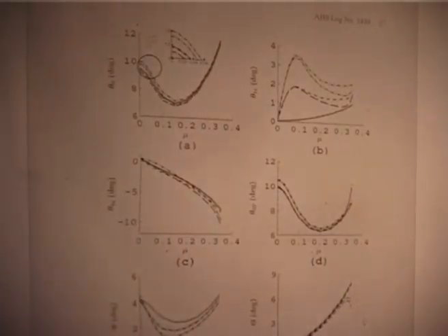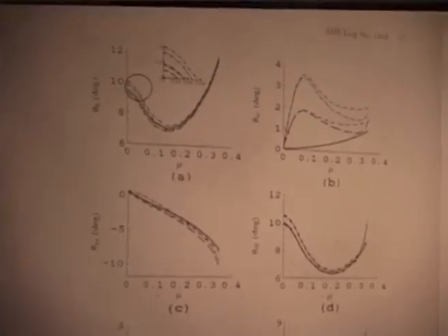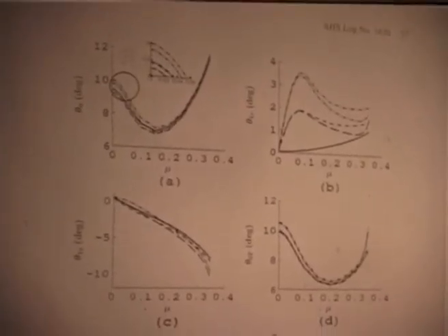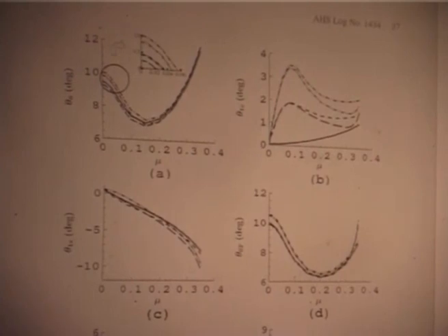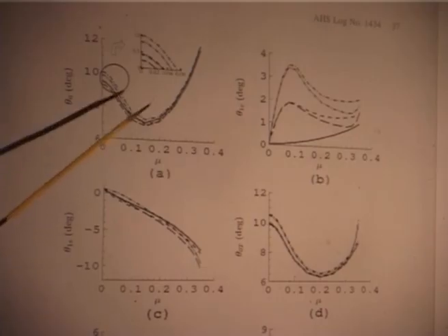That means, even if the vehicle has enough power, the helicopter cannot be converged, in the sense trimmed properly, because it requires a very large control. Now, why does this curve shoot up like this? That is because of the fuselage drag.